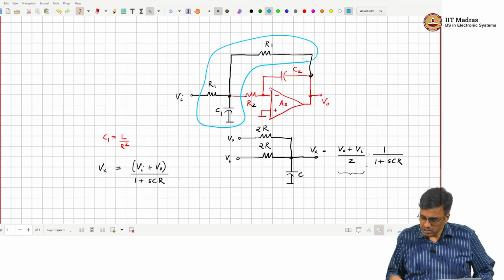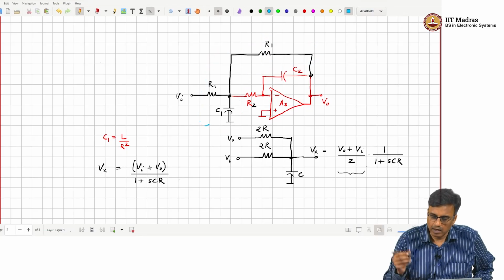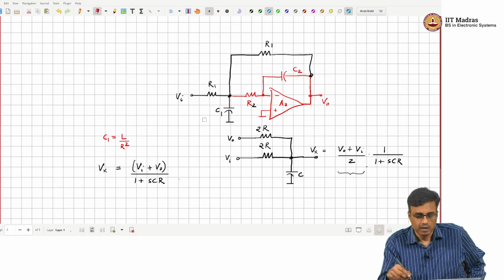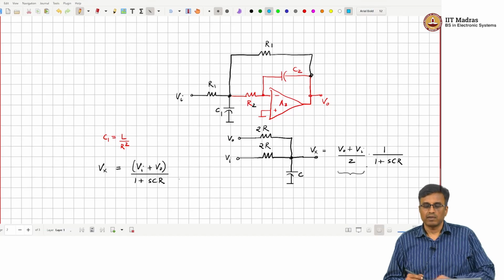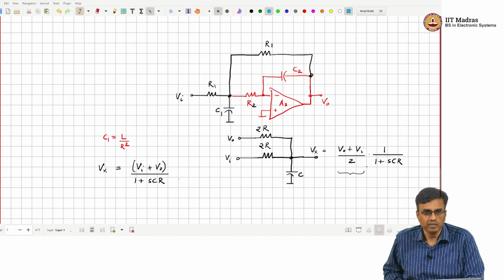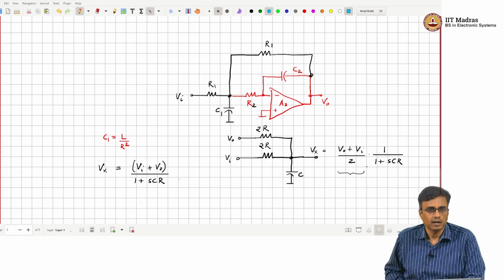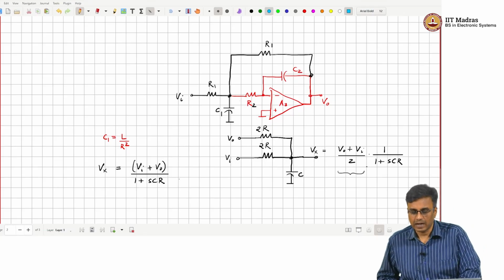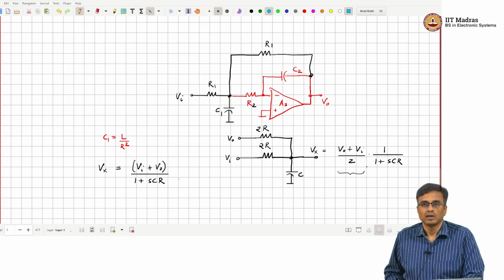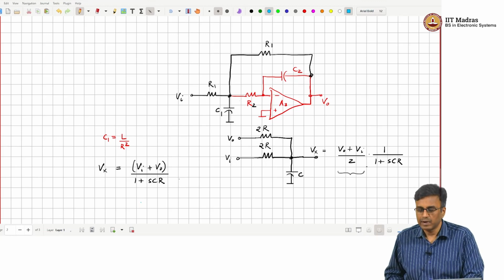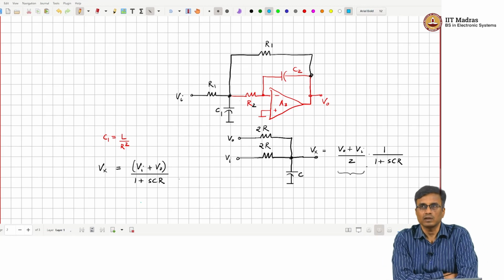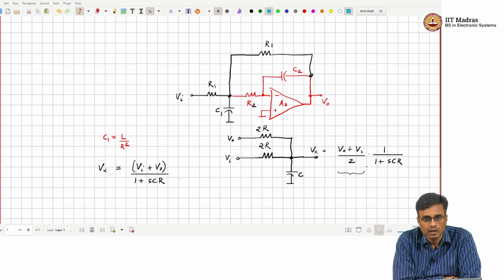This is a very useful circuit when you are building filters on PCBs, where every extra op amp and every extra component costs space and money. This gives you a second order filter transfer function with only one op amp. What comment can you make about driving another stage? If we load up VO with a resistor, what happens? It does not change the transfer function.